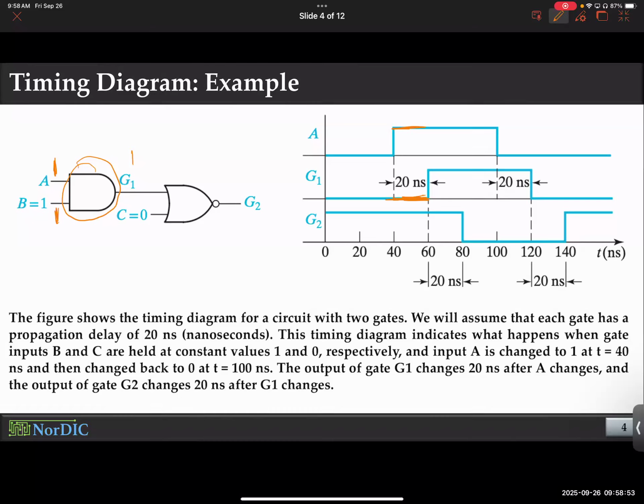So the drain also has capacitance. The output is taken from the drain, and it takes some time to charge or discharge the drain capacitor as well. It takes some time to charge up the input, and then it takes more time to change the output. So that's why there is a delay. Even when the input changes, the output will take some time to change. So meanwhile, G1 will stay where it was. It's like there is an inertia. It doesn't want to change.